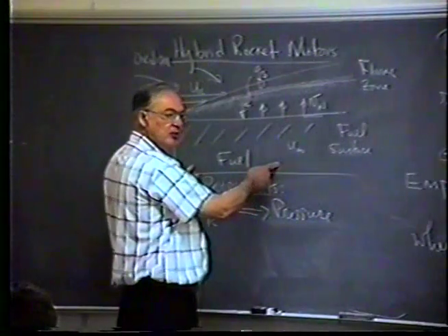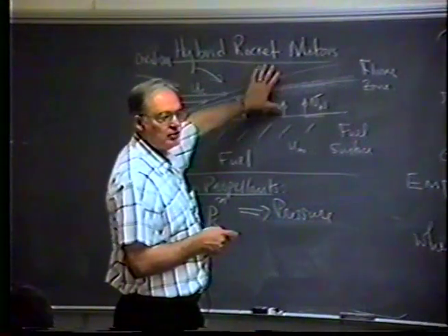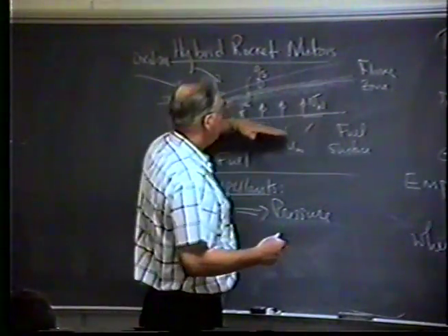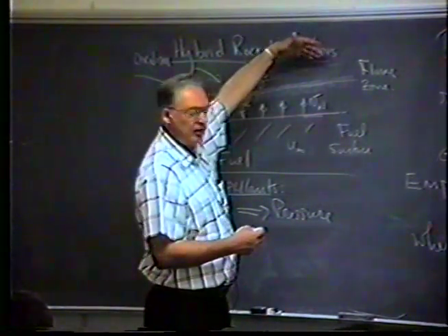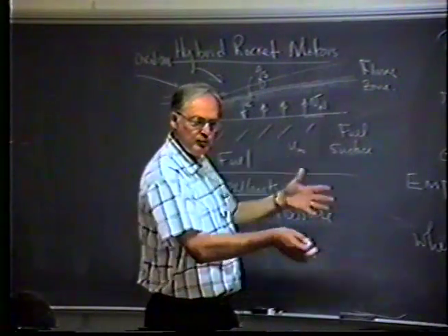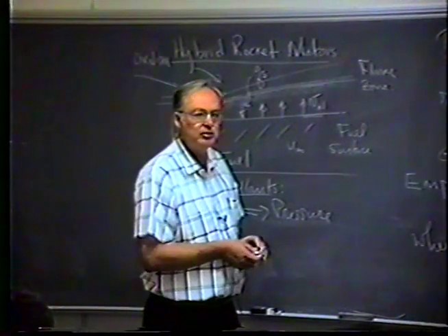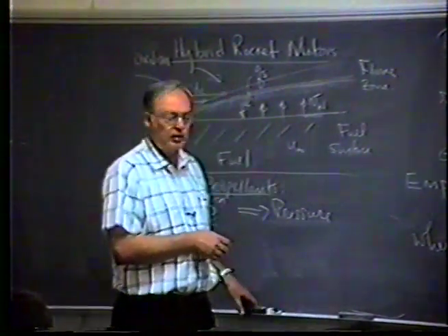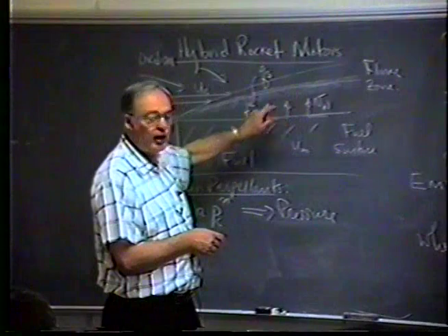No, because you'd have a solid rocket that was going. Now, there are ways of turning off the combustion of the solid rocket, and that's by depressurization, where you open up the port on the chamber. The pressure drops and it pulls the combustion front away from the surface and extinguishes the combustion. The problem is that the insulation inside the chamber and the solid propellant fuel itself have absorbed a lot of energy, and so they continue to vaporize and reignite the mixture. So starting and stopping solid propellants for controllability is a difficult thing, and that gives you motivation for looking at configurations of hybrids that allow you that controllability.